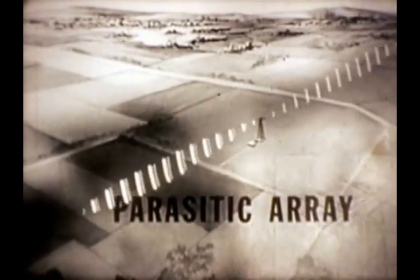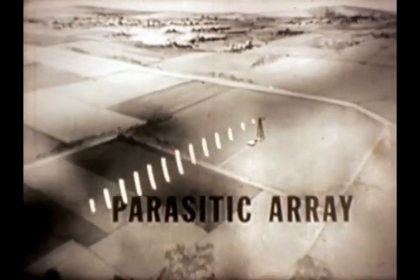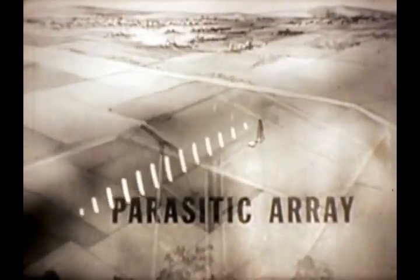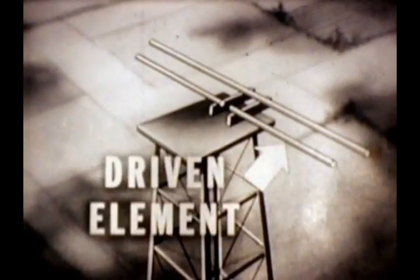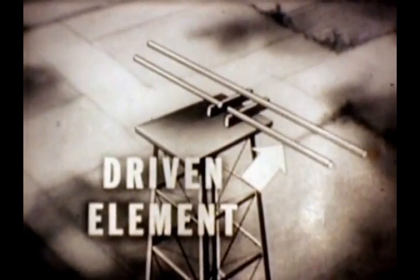But should your problem be to transmit energy in just one direction, an answer is the parasitic array antenna. In this array, the elements are aligned like those in the end-fire array. When two elements are used, the only element connected directly to the transmitter is called the driven element, which is a half wave in length. The second element is called a reflector and is longer than the first. Let's symbolize the driven element with a fluorescent tube and the reflector as a mirror-like surface.